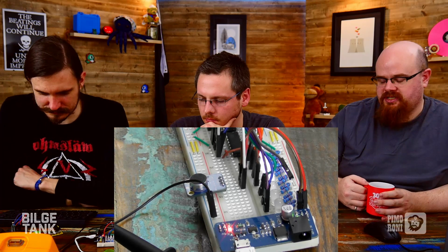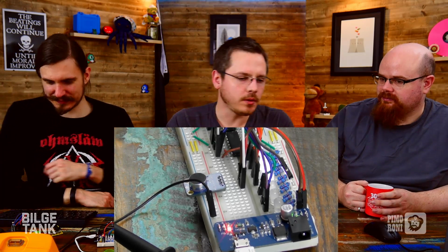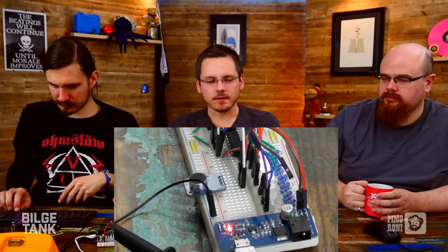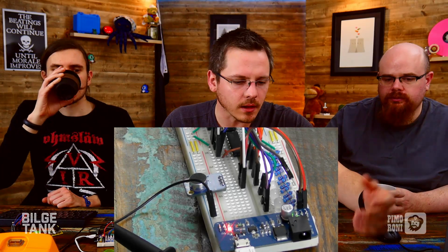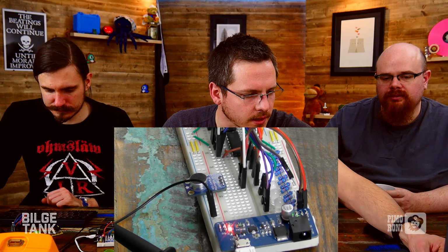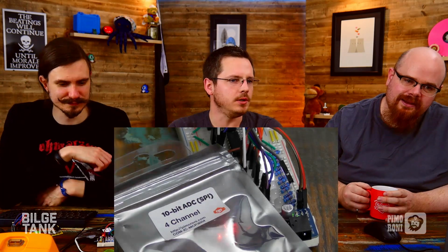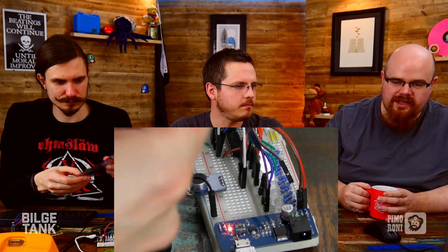So next step up, actual ADCs in use. Yeah, well, obviously that's roughly how it works, but if you want to put it into your project, you're almost certainly going to use either a breakout board or a DIP chip package. We sell Microchip parts, I think. Yeah, MCP3004, which is a very popular ADC chip for hobbyists. That's basically a 10-bit ADC with an SPI interface, so you don't have to do any crazy messing around. So SPI, perfect for Arduino, perfect for Pi. Yep. Arduino and Pi both have SPI